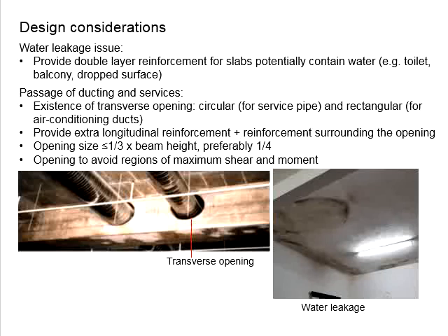This way, at least you can ensure that the capacity of the beam is not significantly affected. For more information, you can read certain publications which you can find online. They have specific research on this. As a rule of thumb, preferably it will be 1/4 of the height, as given by a typical researcher. Some would say that it will be 1/5, but what the industry normally practices is 1/3. This will be very much dependent on your confidence level in the quality of the workmanship by the contractors.